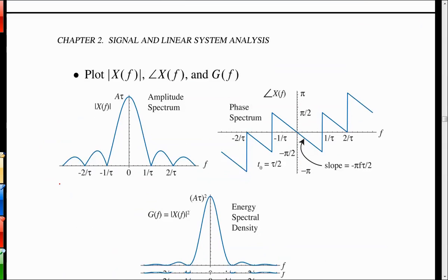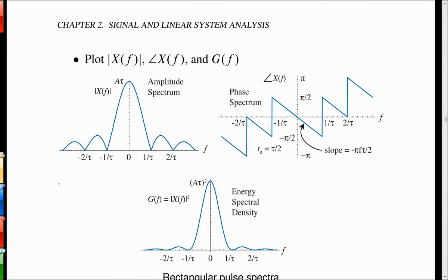And then this is the spectrum and the phase. It's the continuous version of the line spectra for the pulse train. So it has this sinc function shape, only now it's continuous. The nulls are at multiples of 1 over tau. The phase has the sloping business from the t naught. And if you draw it a particular way, like here, I picked a particular value of t naught, then you get this phase slope, and you get the wrapping and things like we were looking at before.